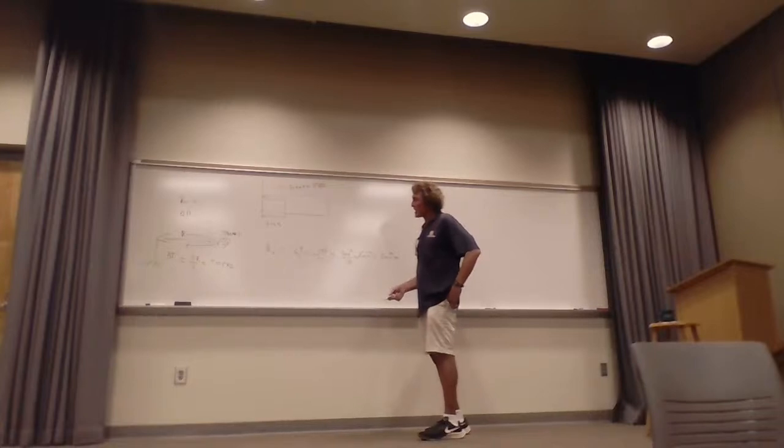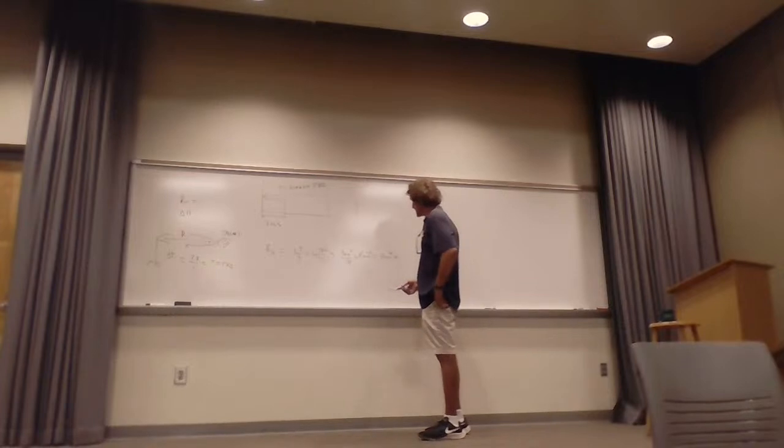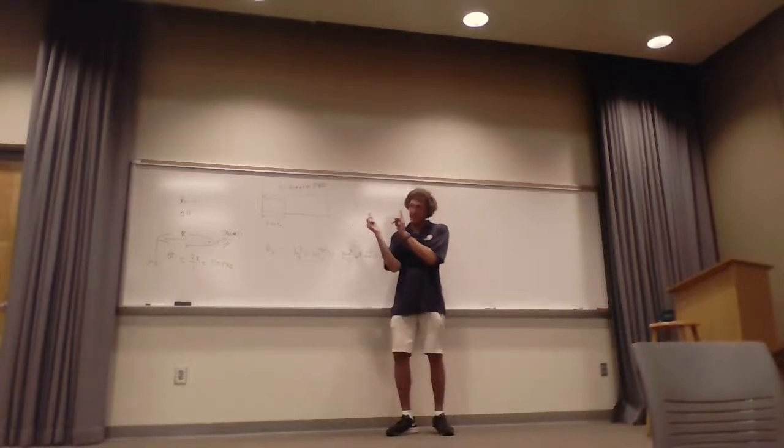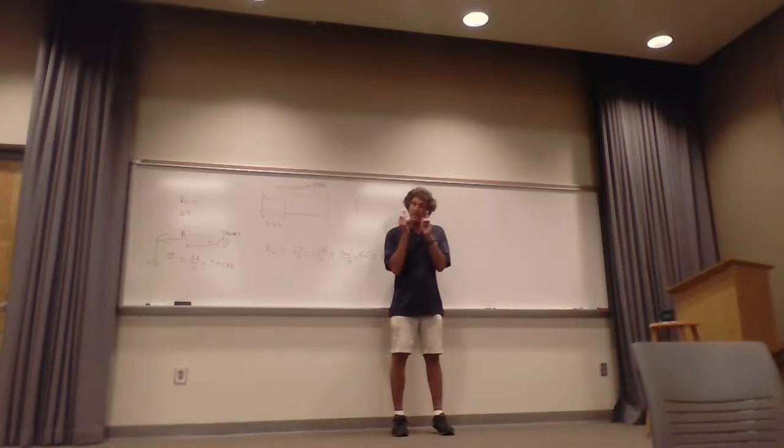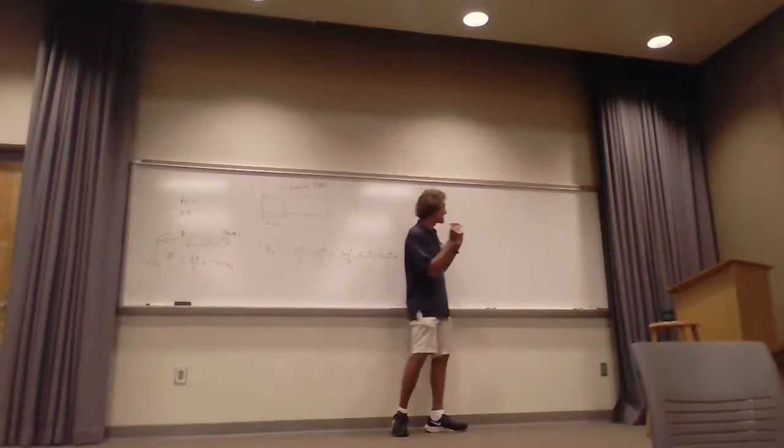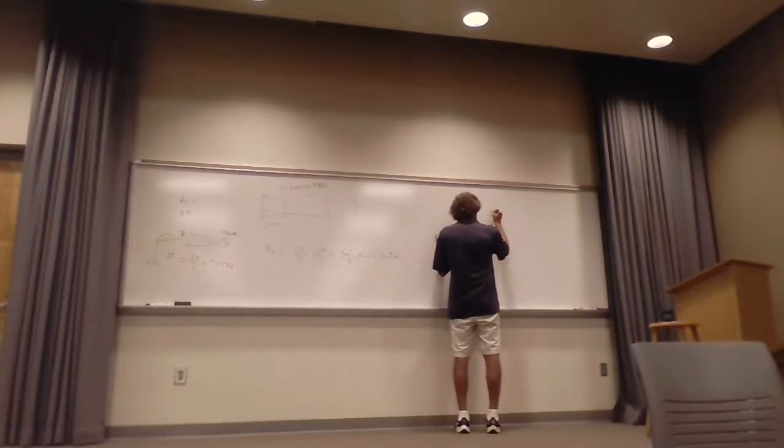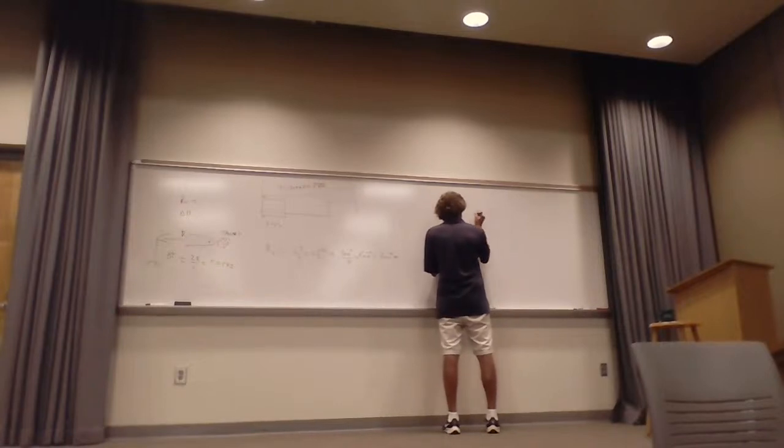In a similar way, the delta R, the range resolution, if you just think about this, as a pulse is coming down of a certain width, as it's hitting, it's reflecting, right? So think of a time T, set it equal to 0 when the pulse hits there. In other words, this is a target. Take a snapshot of time, and this is what the pulse looks like just as it's hitting it, right here. So it's got a width tau.